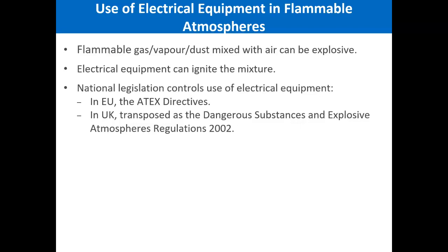And if there is more than 40% H2S in the air, again, there will be no fire, there will be no explosion. But if the percentage of H2S in the air is between 4 and 40%, it will definitely catch fire and cause an explosion. Same thing is with dust as well. Dust also has its flammability limits. Vapors have their own flammability. So every type of fuel gas or every type of fuel has its own flammability limits. So that is very, very important to remember as well.